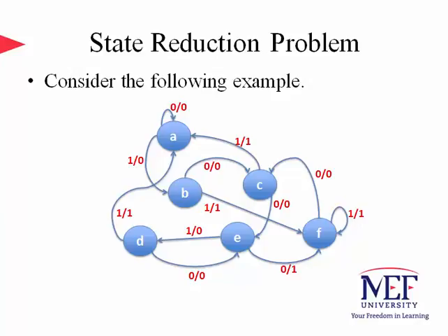State reduction problem deals with reducing the number of states in a given state diagram while keeping the input-output relationship unchanged. To be able to understand how a state reduction algorithm works, it is best to review an example.